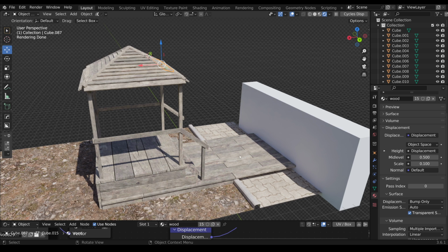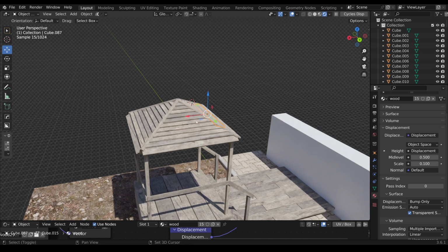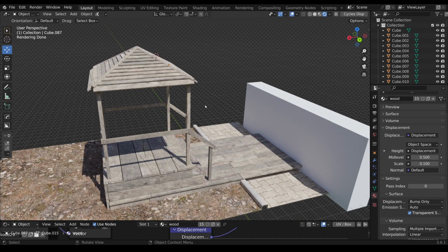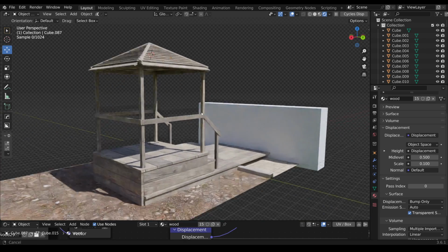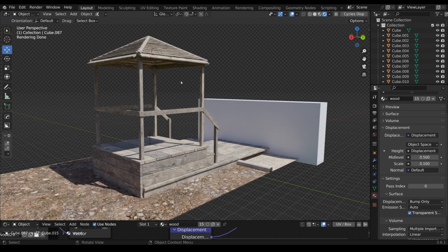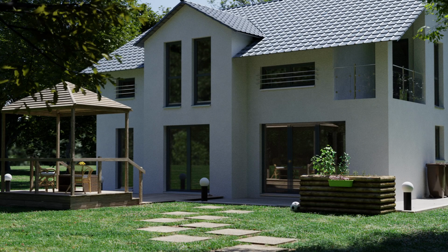Pay attention to when you use Shift-D and when you use Alt+D. Use Shift-D when you want to copy the object independently, which is probably how most people generally use it. Use Alt+D when you want to copy the geometric properties as well. What we also did was copy the roof at the top. We also copied the Boolean object, ensuring that the modifiers or Boolean objects that were created for the second slope are the same duplicated Boolean objects. These are sometimes many small details that can speed up such tasks significantly.